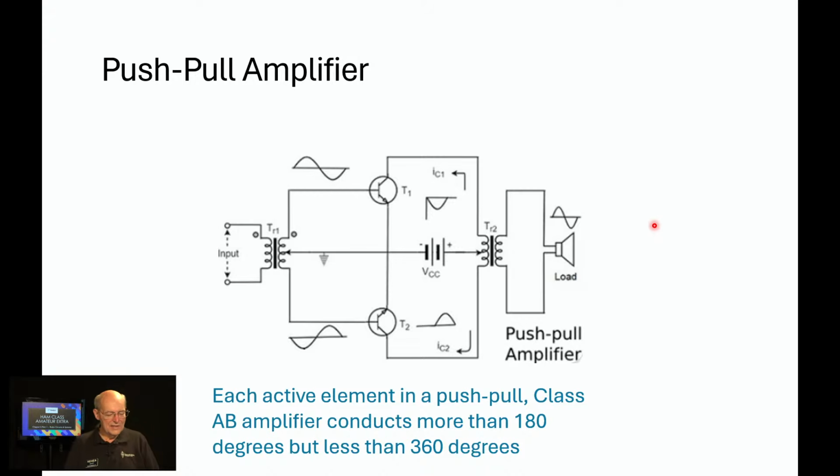There's one other concept that I need to share because it's a pool question. This is kind of a strange bird, or it looks like it. We've got two different kinds of transistors, and we've got a circuit through a transformer. We've got input waveforms being supplied. Now, the way that the transistor is biased, this transistor is only going to be conducting on the negative peak of the input cycle, this one on the positive peak, but they're recombined in the output transformer to produce a waveform that is back to looking like the input waveform.